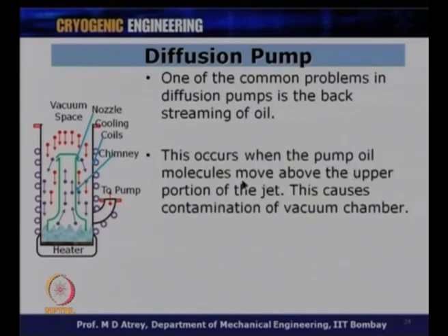This occurs when the pump oil molecules move above the upper portion of the jet. This causes contamination of the vacuum chamber. This is not permissible for certain applications, and therefore, in those cases a diffusion pump cannot be used.